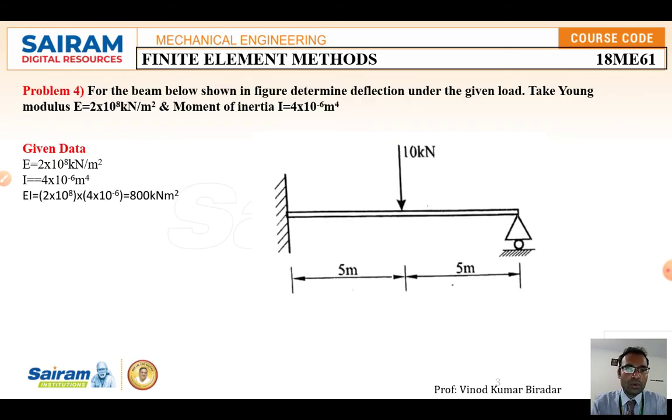In the finite element model, by looking at the diagram only, you have to analyze what to calculate and what not to calculate. That is most important here. Look here, I am just giving a hint. This is the beam element. Here one end is fixed and here a roller support is there. Completely fixed means, as I already told you, wherever fixed is there you have to delete the respective row and column.